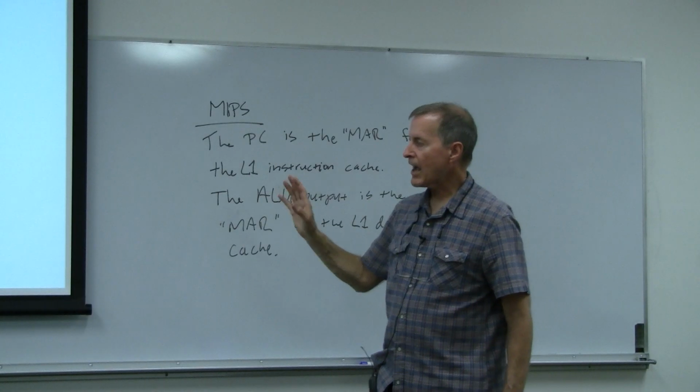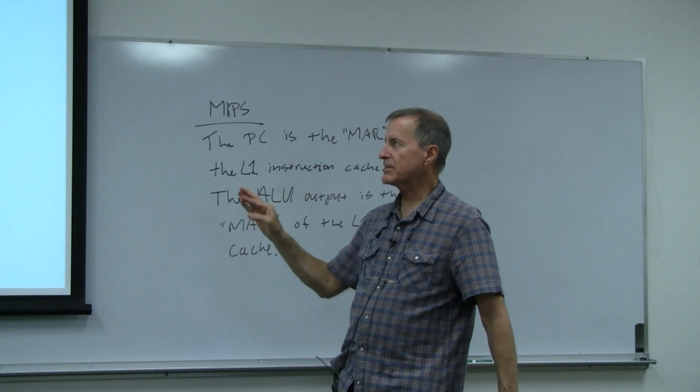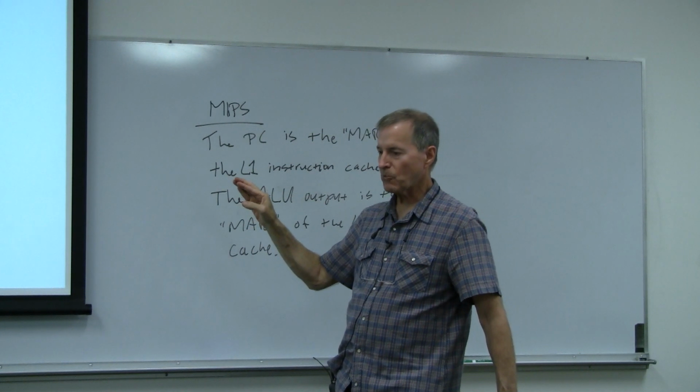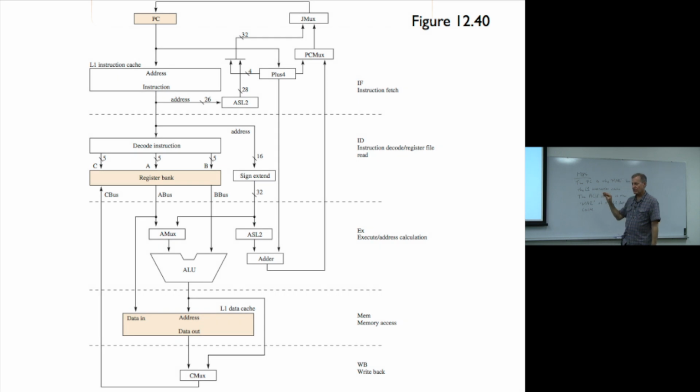All right, so now let's get back to our original question. How many clocks are there? How many registers here do we have to clock? What parts are sequential? What can we clock things into? Yes, the data cache. If you want to clock something into memory, there is a clock input to the data cache.